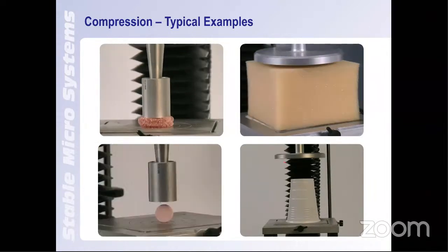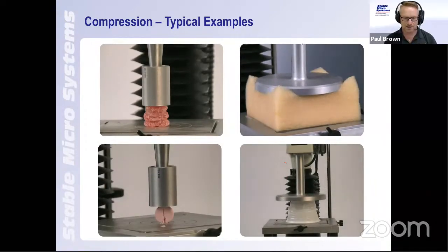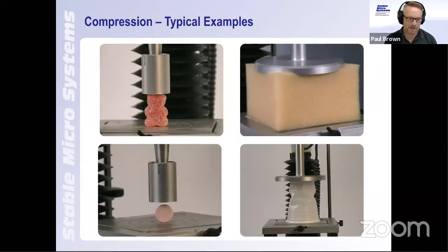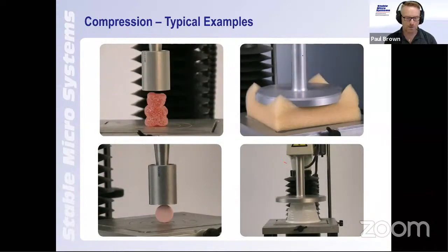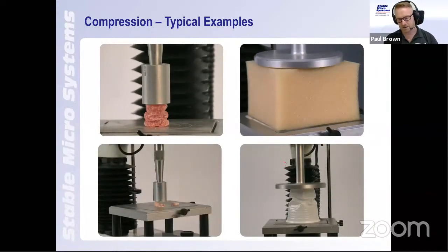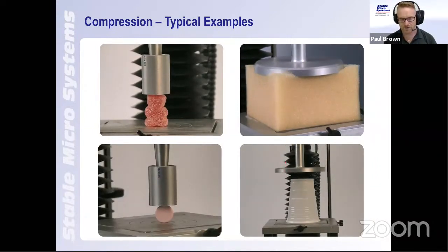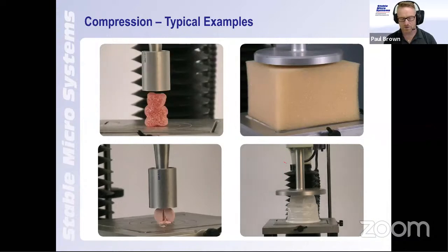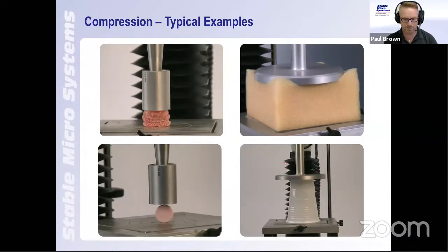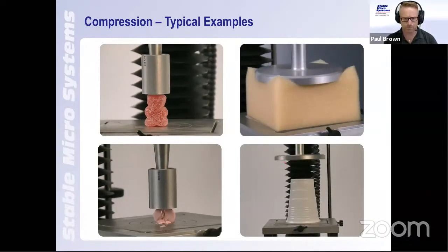One thing to remember here, and also with penetration, is that quite often once we have created a compression test, we are unable to retest that product because we actually take the test and we compress or we change the structural properties of those items. So once we've made that test, it's not possible to retest that same sample. But just some examples of how compression works.